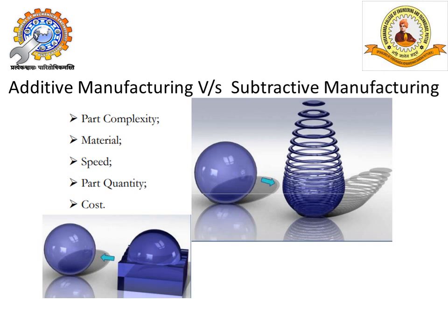In the first diagram, a spherical ball is obtained by removing the material by a machining process. The second one is the additive manufacturing process, which follows a layered approach. The material is added in layers, and these layers are clubbed together to form the component.